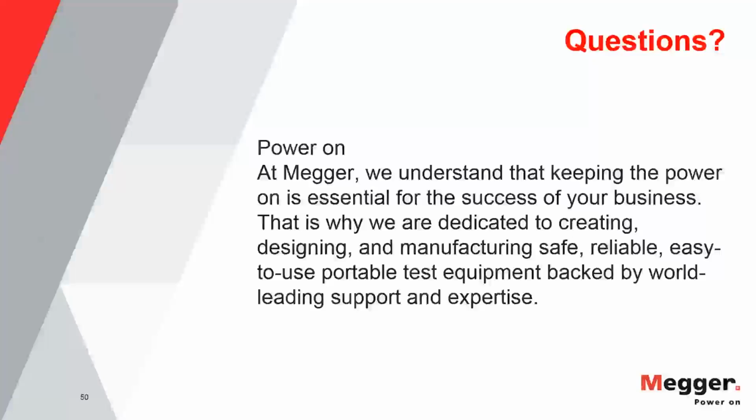Okay, yeah, that references back to what Jason said initially. All of that was explained in detail in that webinar before. So if you need more detailed information, take your time and watch that webinar as well. To answer that in short, the PD test is the only test in the diagnostics world, so to speak, that can localize defects. The way this is done is based on TDR technology, or radar, if you want to call it that. And with that come all the strengths and all the weaknesses of typical radar technology. The localization is done, as Jason showed in some of these slides, by evaluating the reflections and the run times between the different pulses. So it is actually a true localization of the weak spots and the problems.